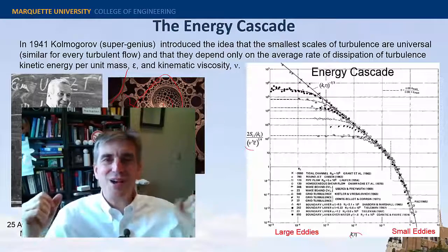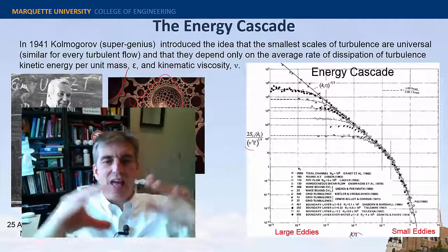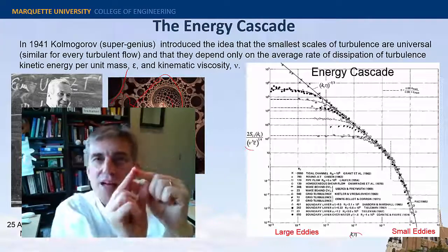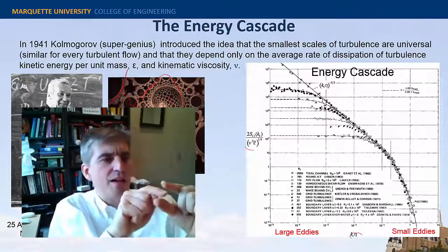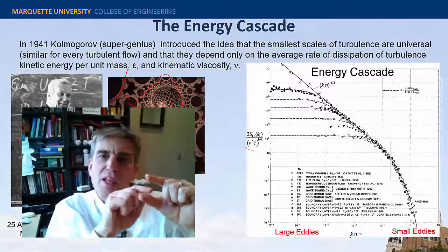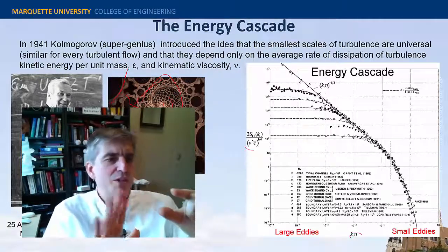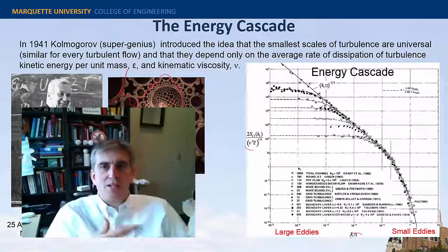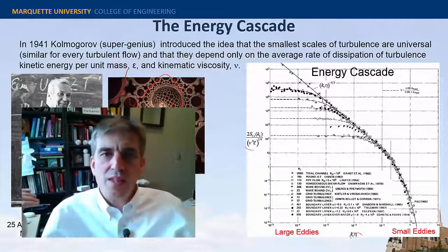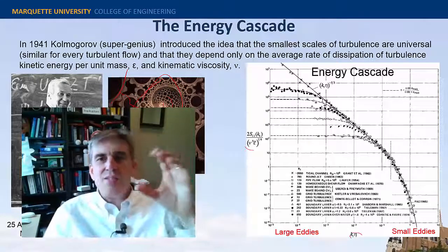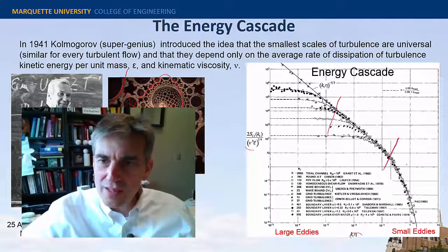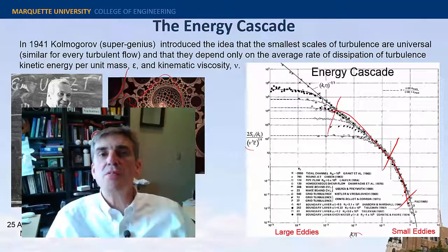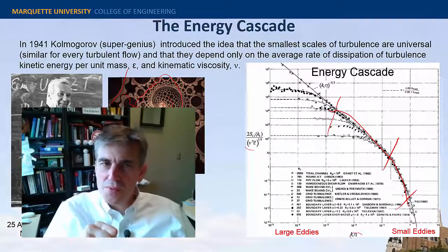All turbulence is self-similar. So that means if I have a flow, like flow over a flat plate, and I zoom in and I look at just a little section of that flow, I can't really tell if those swirls and that formulation and that passing of energy through the dissipation range, is that coming from flow over a flat plate or flow behind a circular cylinder or airflow in the atmosphere. At some scale, over some huge scale length, all flows become self-similar. All turbulent flows become self-similar. So this is a way to grab a hold of turbulence here.